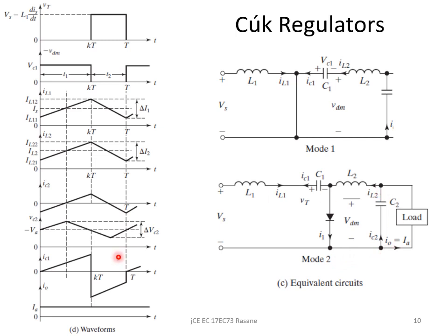Okay. Next is IC1. So IC1, as you know, during the on time, is going to be in a discharging fashion with this polarity shown, right? So with this polarity, it means that the capacitor C1 is going to be discharging through the inductor L2 and capacitor. So we can say that it is rising from here to here. The polarity needs to be looked at.